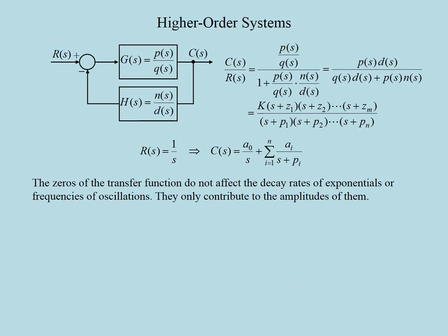Note that the zeros of the transfer function do not play any role in whether we'll have rising or decaying exponentials or oscillations in the response. They also don't affect the decay rates of exponentials or frequencies of oscillations. They only contribute to the amplitudes of them.